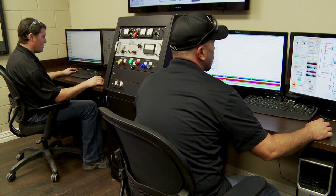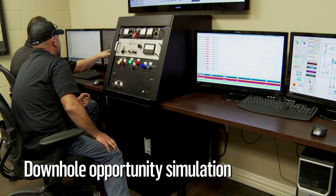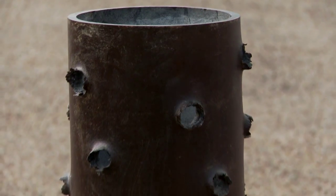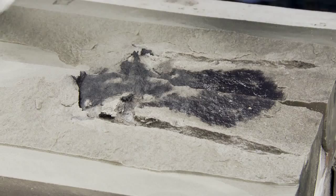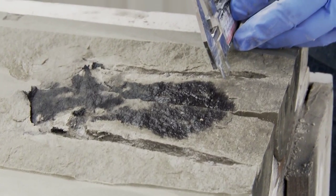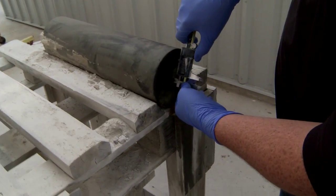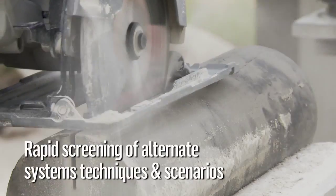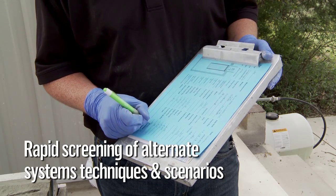Application specialists use state-of-the-art software to construct realistic simulations of your downhole opportunity. We start with a cylinder of rock. We apply stress to the outside, pressure to the inside. We simulate the casing and the cement of the wellbore and the gun, and all of the surges that happen once we detonate a shaped charge and produce a perforation. Geodynamics' commitment to testing based on representative conditions enables rapid screening of alternative completion systems, techniques, and scenarios.